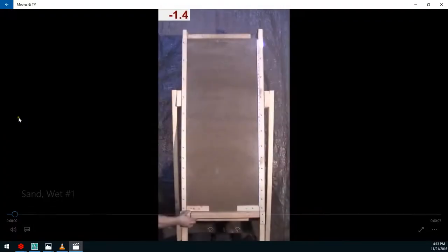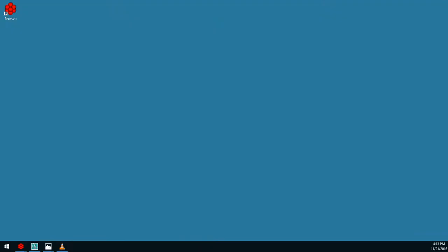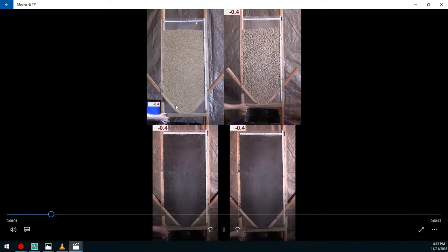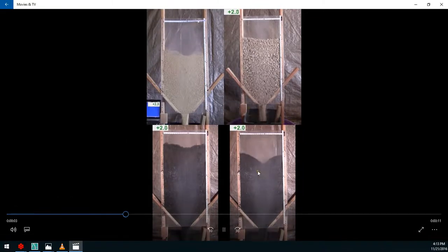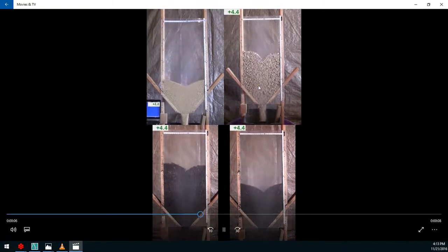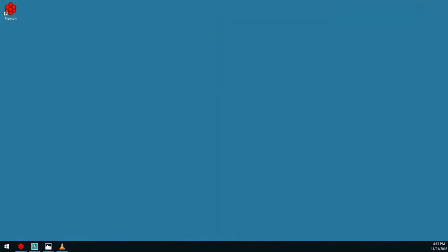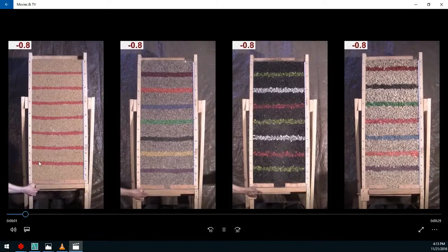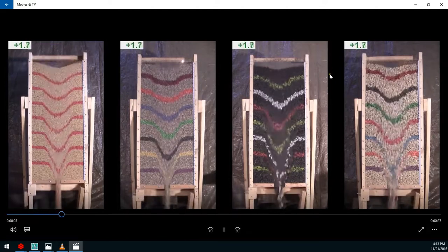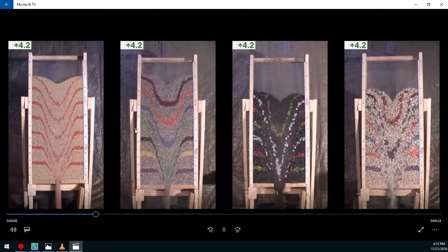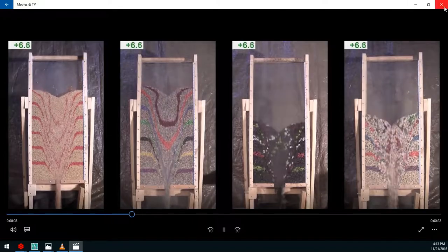This is some fines. This is phosphite fines, actually. Obviously things like playground sand is one of the more difficult actual materials to handle, because you can see it can build straight up like that. And of course, you can do other things, look at various exit angles. These are, again, some standard materials that we work with, and look at modeling those. Here's another whole range of different materials in full-size flow testers, from limestone to P-rock to coal again.